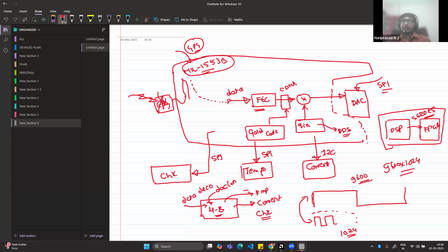So even a sinusoidal signal, like a DDS signal, we have to configure, because we need to set at what carrier frequency you want to transmit. There is something called the frequency tuning word, FTW, that we configure. Then multiplication, and send it to the DAC. This is a parallel interface, so all these things we put into the FPGA. Whatever the configuration parts are, like temperature sensor, current sensor, clock, and DAC configuration, we put into the processors. Everything we put into software works at the slower speed.